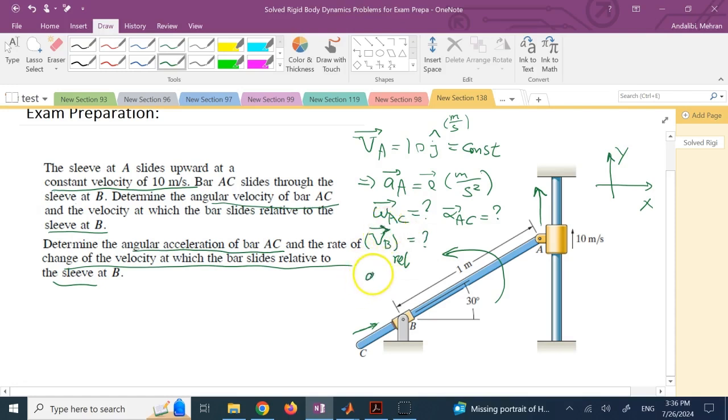And A of point B relative. Again, relative to member AC, because B is a pin point, so relative to the ground, it has no velocity or acceleration, but relative to this moving member AC, if you attach a camera or any object that measures velocity or acceleration on member AC, you'll see that point B does have a relative motion. We are after those relative velocity and acceleration terms.